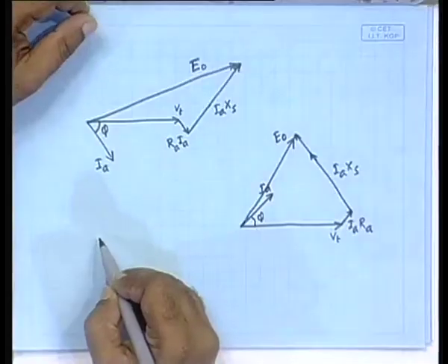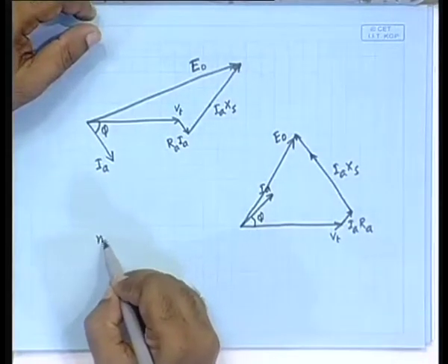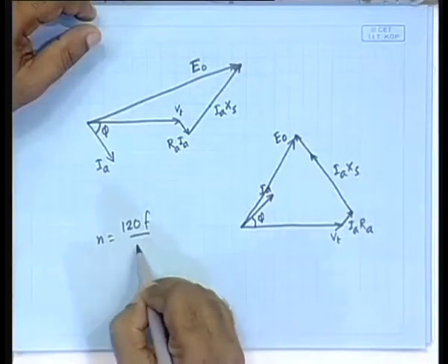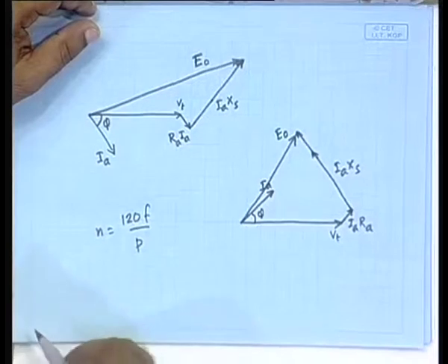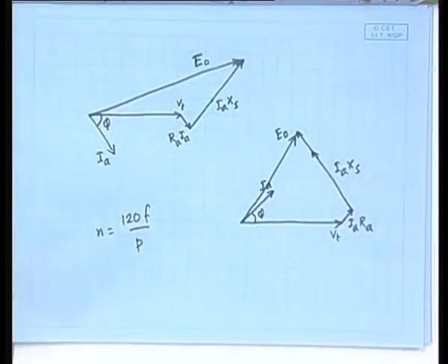So, if this point is understood, then you might argue, why not use a synchronous machine. The reason that we cannot use synchronous machine is that in that case the speed of rotation is hard, in a hard way given by the grid frequency. The grid is at 50 hertz, and therefore, the speed of rotation is N = 120 f / p, where p is the number of poles here. So, the speed of rotation will be hard at that amount. In case of the induction machine, it could at least be varied to some extent. Here that scope also does not exist.